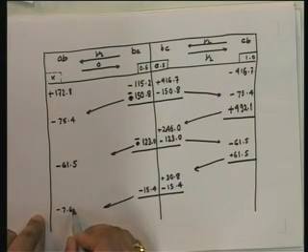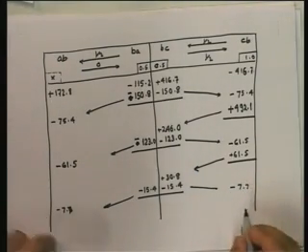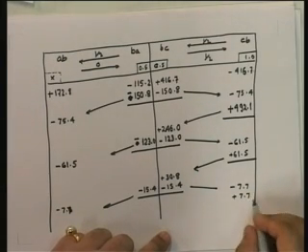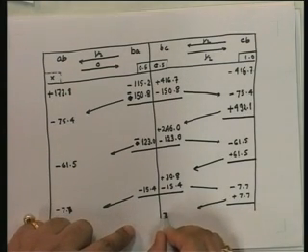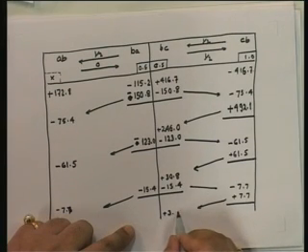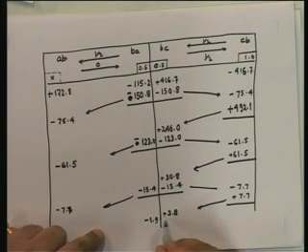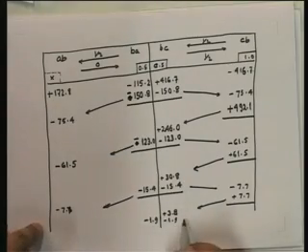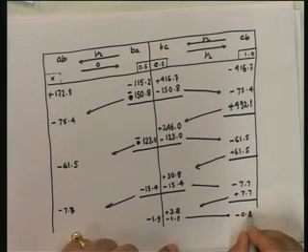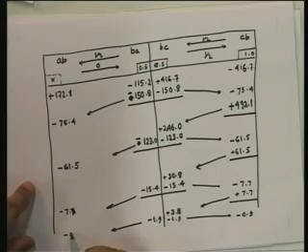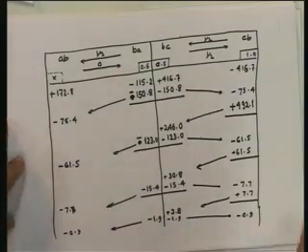So minus 7.7, minus 7.7. This gives an unbalanced moment here, plus 7. So this now carries over here, plus 3.8. See, when you get unbalanced here, you require minus 1.9, minus 1.9. Again, balance, minus 0.9, and here you get minus 0.9. This way you continue, okay, till you get 0, 0, and then what do you get as the final value?